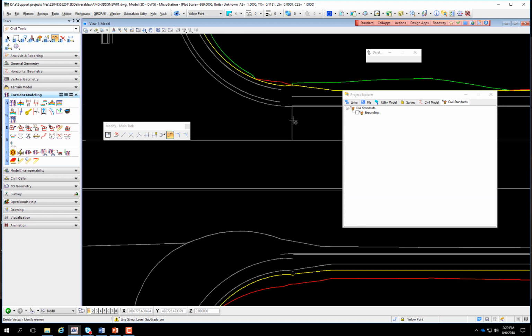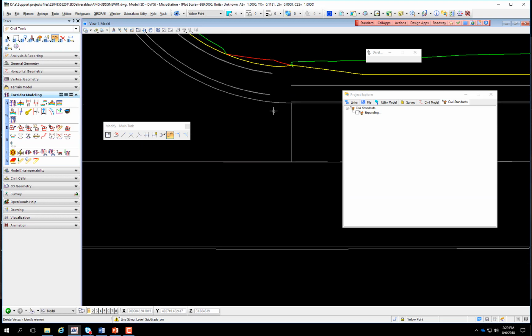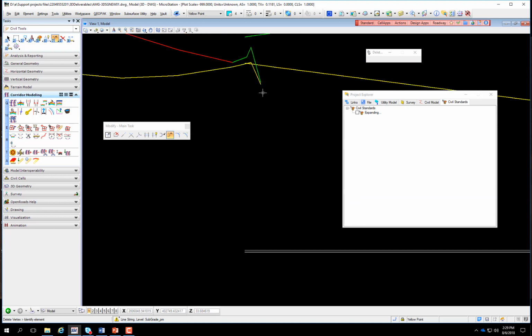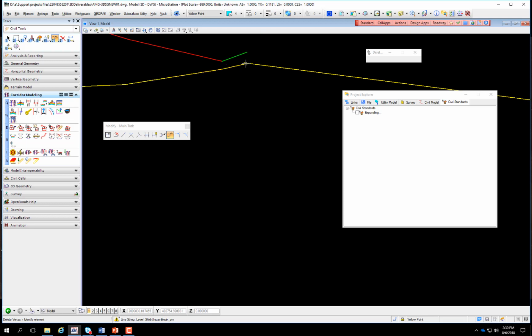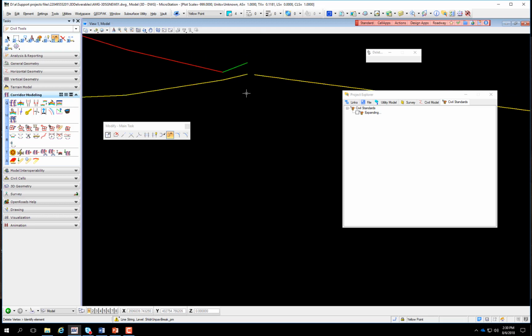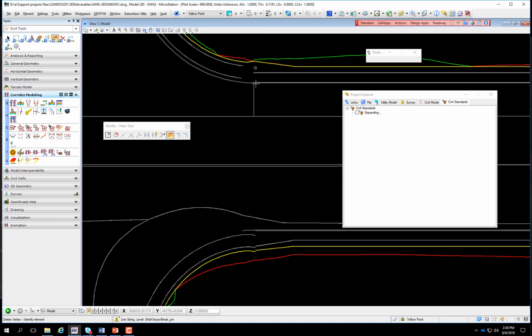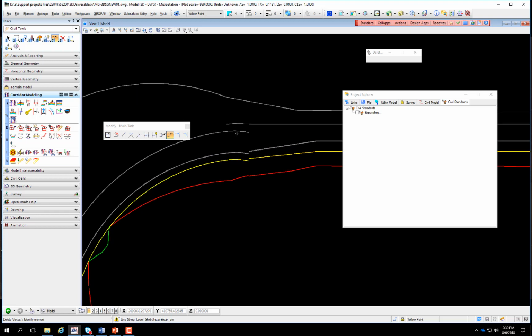Anytime there's a crossing break line somewhere like over here, sometimes it's not as easy to do it in the template, so it's easier to just do it from deleting vertices to get cleaner surfaces. Here's another one where I probably would just delete that whole element.